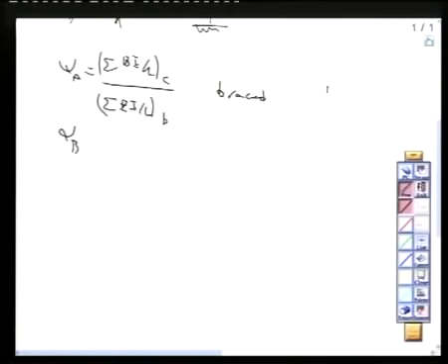What are the limits of K? It is between what and what? Between 1 and 0.5, not 0. Between 0.5 and 1. That's why for braced structures, it is immaterial whether you take K equal 1 conservatively or you calculate it exactly.